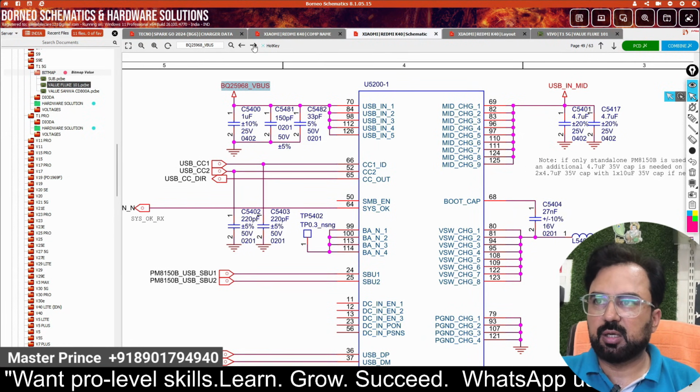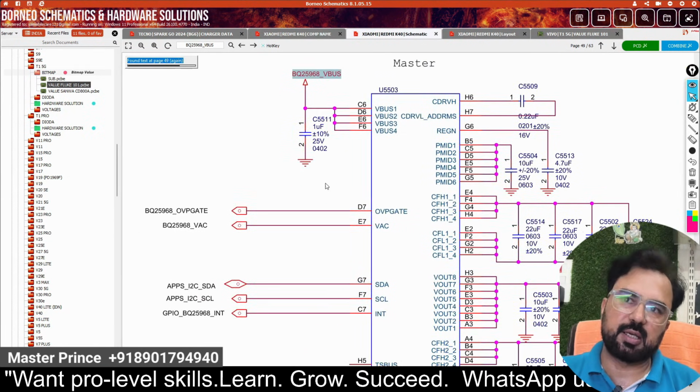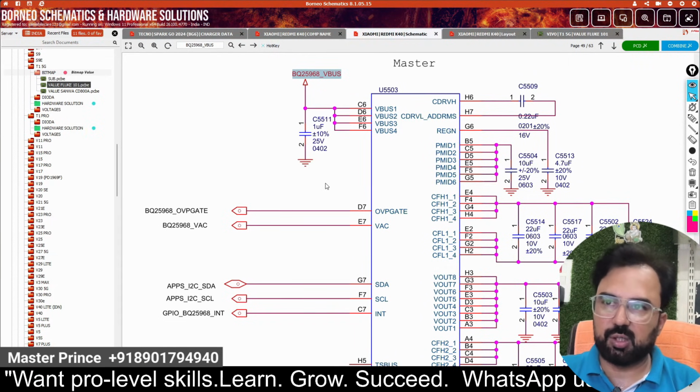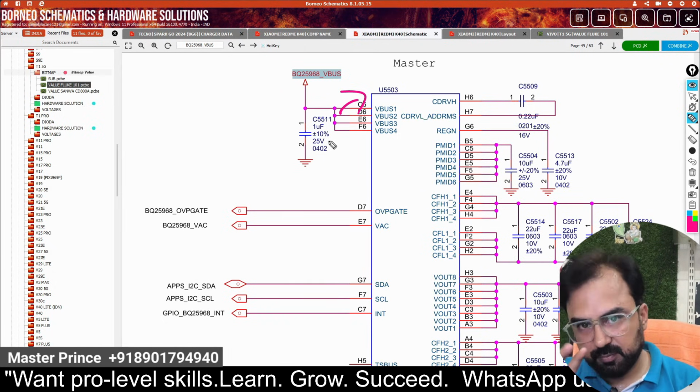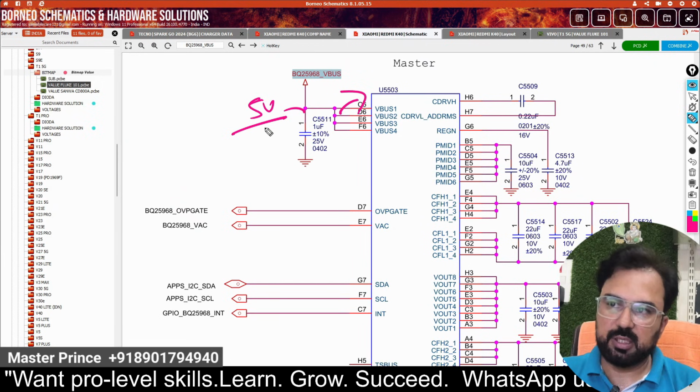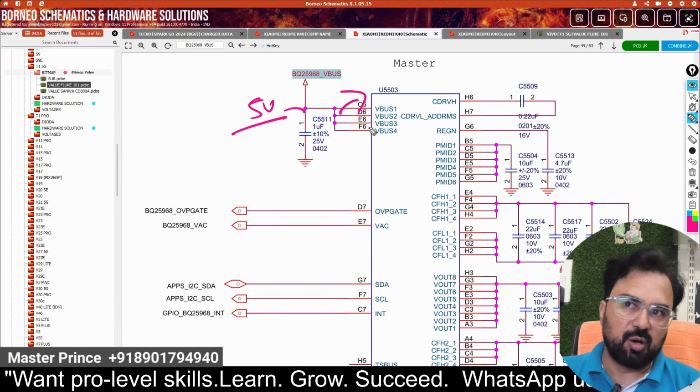So we connect again. Now this is the secondary IC. Now I will explain which lines are responsible for this fault. First of all, if the output V bus does not connect, say you get 5 volt entering here but it does not connect to these pins internal to the IC.